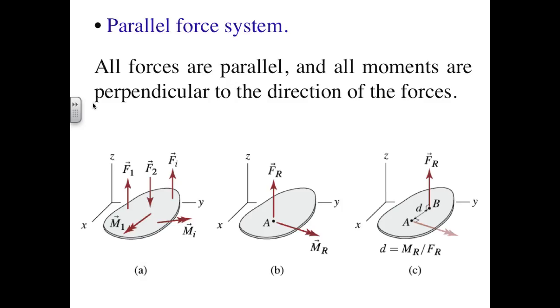So this figure shows our shift in the resultant force as being from A to B. If I just slide this position vector out a little further and use the right-hand rule to take the cross, we'll see that we do in fact get a resultant moment in the correct direction. So we need to shift it from A towards B in the direction shown into the background now rather than into the foreground. And again, we've used the scalar approach to find the magnitude of that shift as the ratio of the magnitude of the resultant moment to the magnitude of the resultant force.